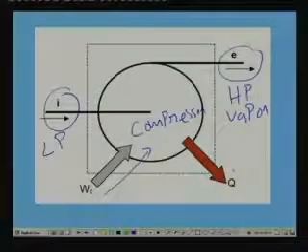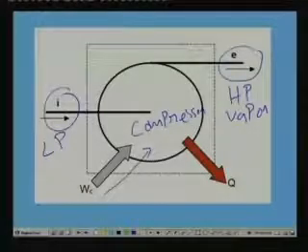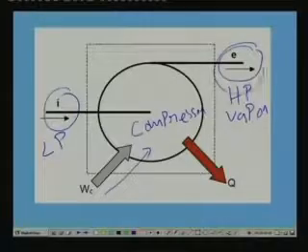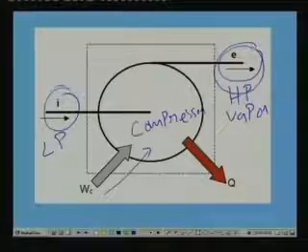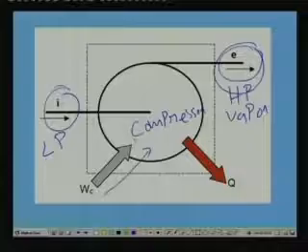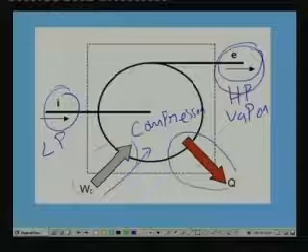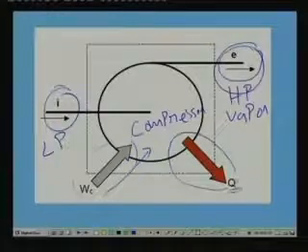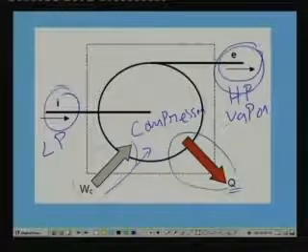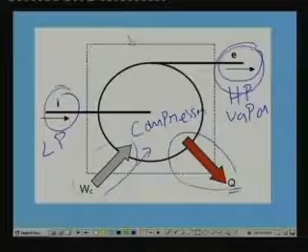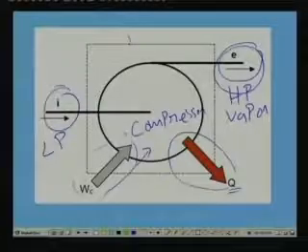If you look at the energy flows, you have the energy flow by means of mass flow at the inlet and mass flow at the outlet, and you also have energy input by means of the work input, and the energy interaction between the system and the surroundings by means of the heat transfer rate. So this is the system and this is the control volume, and to this we apply the steady flow energy equation.